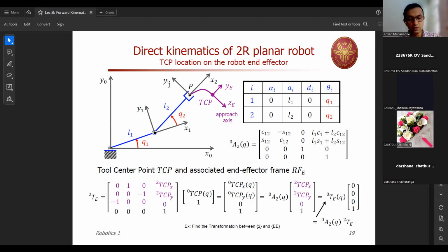So this is one principle in the standard DH representation, right, of the manipulator. So don't forget that. There are other things you need to remember. That is, you start with the joint and then the link. So joint 0, link 0. In fact, there's nothing called joint 0. Joint 1 is the first joint. So you have link 0, which is the ground or the table or the base where the robot manipulator is actually sitting.